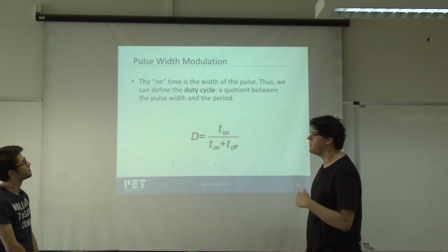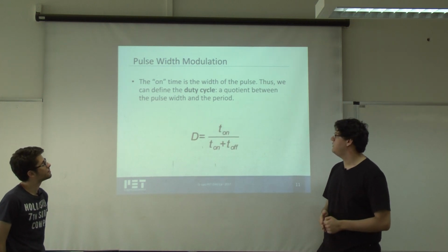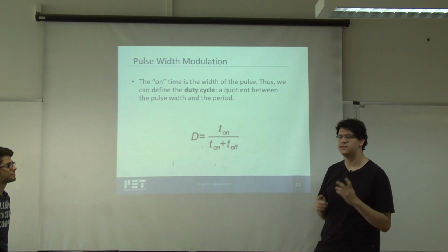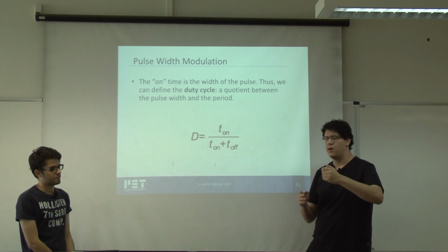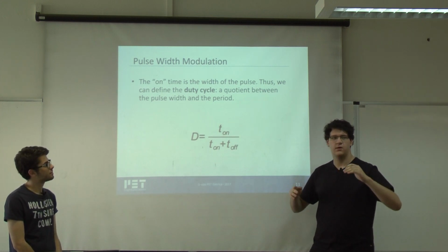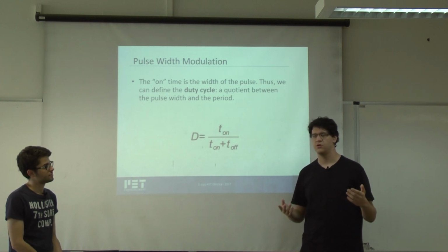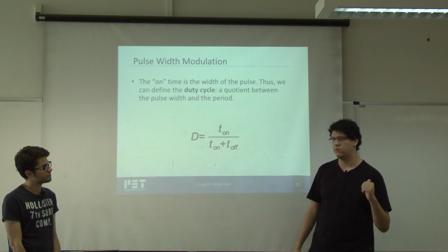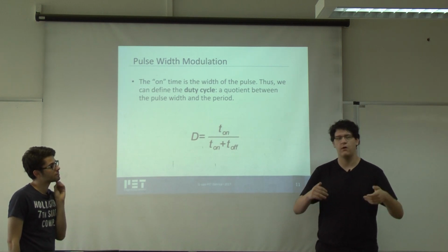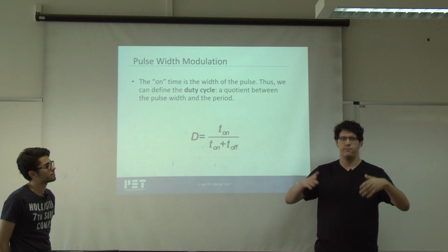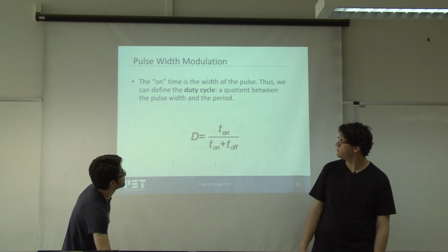And in our calculations using PWM and such techniques, we establish the duty cycle, which is the time in which the power is switched on, divided by the total period of your PWM. So you can set, for example, with a 50% PWM, half of the motor's peak power, for example.